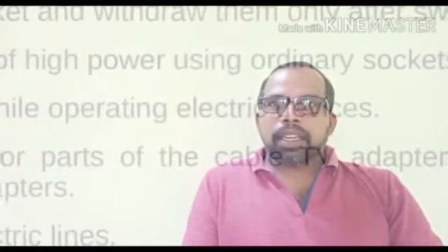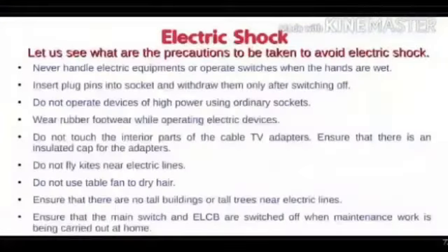The following are the precautions to be taken to avoid electric shock. Never handle electric equipment or operate switches when the hands are wet. Insert plug pins into the socket and withdraw them only after switching off. Do not operate devices of high power using ordinary sockets. Wear rubber footwear while operating electric devices. Do not touch the interior part of the cable TV adapters. Ensure that there is an insulated cap for the adapter.